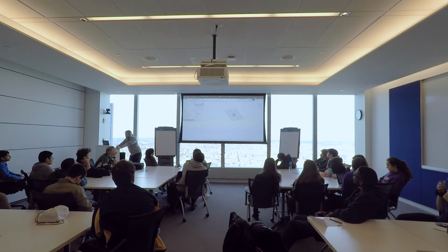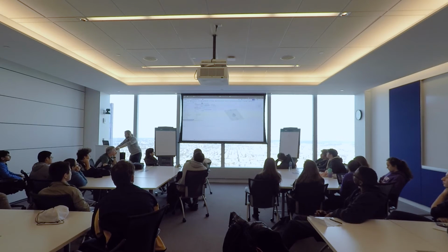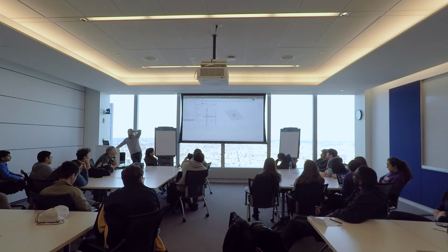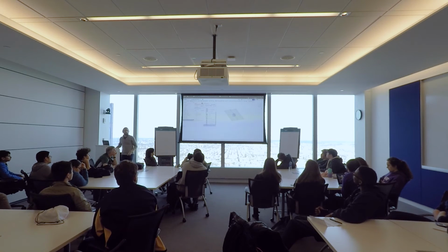I'm going to select a custom beam shape because it doesn't have the standard that I want, the 2x1 tubing. I'm going to select a custom one. I need to find it, which is in my Onshape, and I call it profiles. FRC extrusion profiles. In here, I've just made a document that has a bunch of 2D sketches of different profiles.